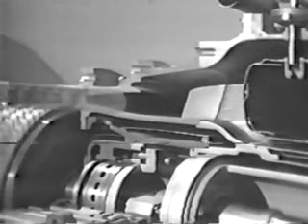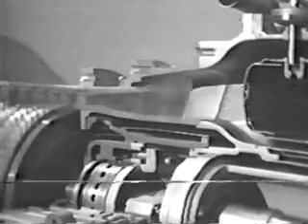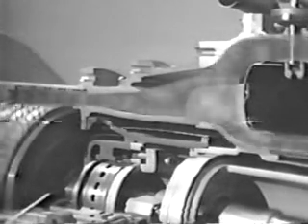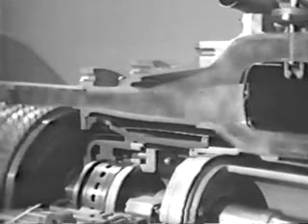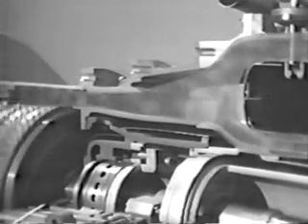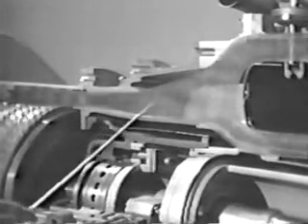After leaving the compressor, another pressure rise occurs before the air reaches the combustor. The pathway the air follows is shaped like a diffuser. The diffusion path increases in area and the air velocity slows down so combustion can occur. It is in this diffusion pathway that the final pressure increase occurs.